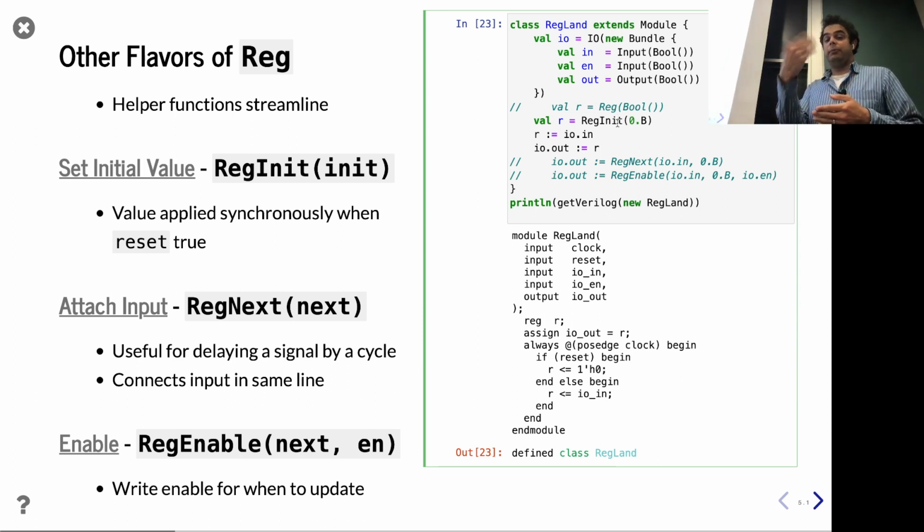So when it comes to registers and latches, a lot of real chips use asynchronous reset, and they were the ones pushing for that. So that was a very commonly instantiated black box. It was so common that in one of the revisions a couple of years ago, they made asynchronous reset now part of the language. But great question. And for latches, I would put them inside of a black box. Yes, question.